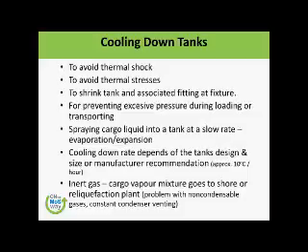To avoid the thermal shock, we want to avoid the thermal stresses on the system, to shrink the tank and associated fittings and fixtures to accommodate minus 161 degree temperature. And of course we do not want any excessive pressure during loading and transporting, and the spraying of cargo liquid into a tank at a slow rate, evaporating and expansion. It is like, we will just spray the liquid. Why we are spraying, I'm going to explain to you in a while.